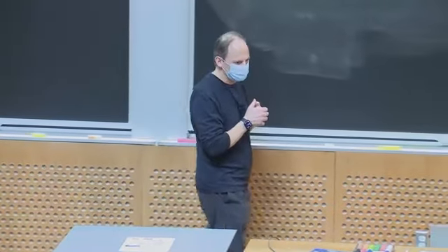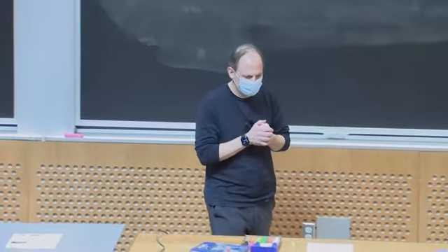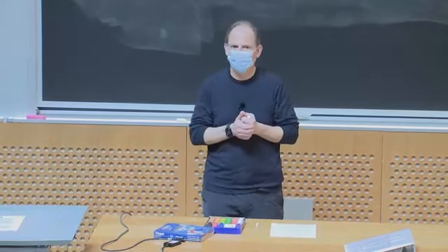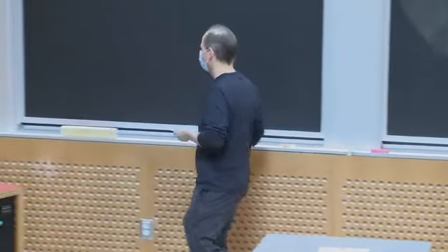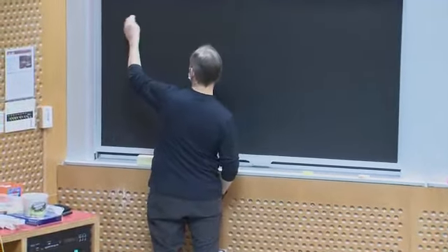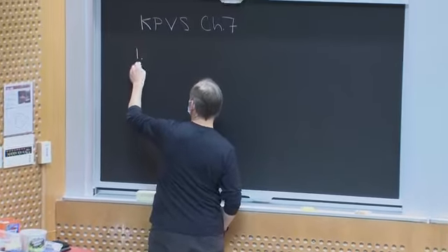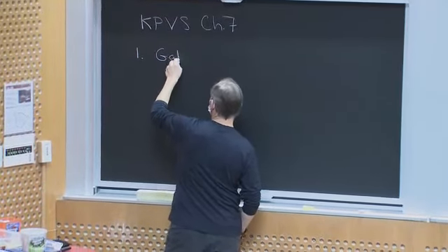And the notion here is, how do we design isolated power converters? When I say isolated power converters, what do I mean? Well, there's kind of three motivations for an isolated kind of topology, or the kind of topologies we're going to talk about today. The first is galvanic isolation.